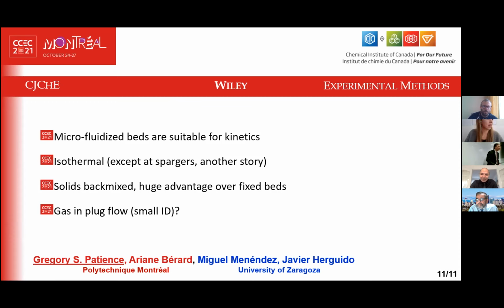My question was about, is it possible to manage the hydrodynamics inside the reactor to be close to a plug flow reactor or mixed? Okay, so the question was, how do you manage plug flow in a working operating reactor? And Steve Jordan, who came from DuPont, was one of the prime driving forces. He said you have to have 30% fines. If you don't have 30% fines, then your bed is bubbling and you're going to get big bubbles. So fines is the answer.